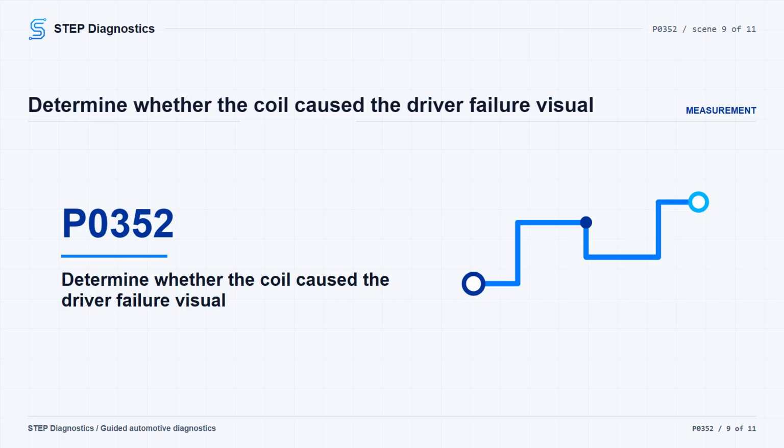Turn the ignition on, erase DTCs, then start and run the engine for up to 1 minute. If the engine will not start, crank the engine 3 times for 10 seconds. Read DTCs again. If a correlating fault sets for the new coil location, replace the ignition coil, replace and program the PCM, then verify the repair. If no correlating fault sets for the new coil location, move on to connector and terminal checks.